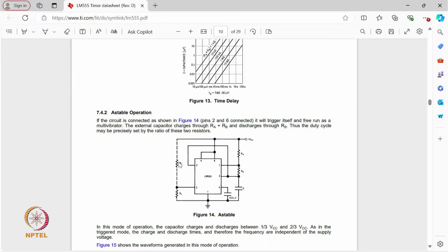These are connected through dotted lines, so we can ignore them for the time being. We will not use these components. So, we use only this component LM555, 2 resistances RA, RB and 2 capacitors. So, these are all the components we need to create this PCB.